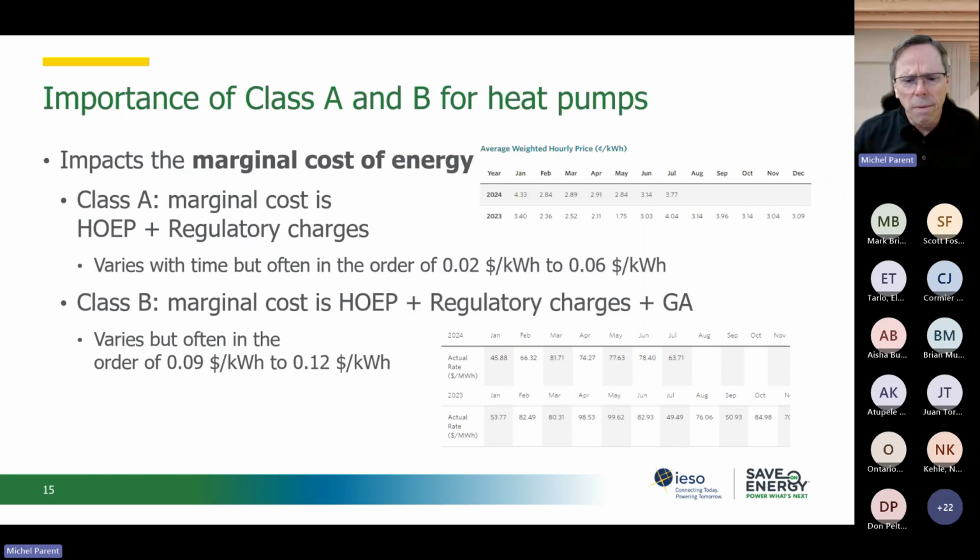So I'm located in Quebec, and I can tell you that in Quebec, heat pumps have been used for like 50 years in a hybrid type setup because of our demand charge. Our demand charge is quite high. Our energy cost is quite low, so people will use heat pumps, but they will always manage the peak demand by using some form of supplemental heating that typically will not be electric in order to make that heat pump the most economical. And obviously, it's still very, very efficient. So that's about the rates. So your rate structure is important.